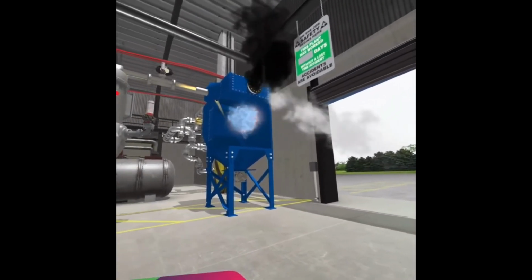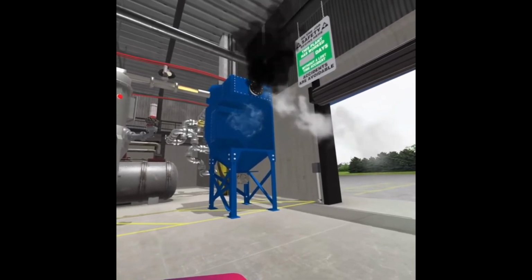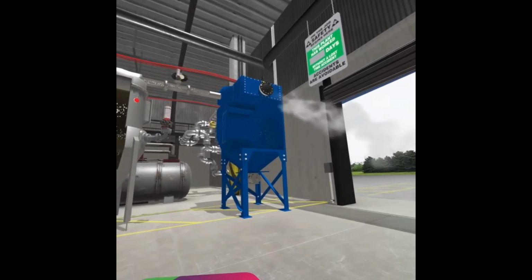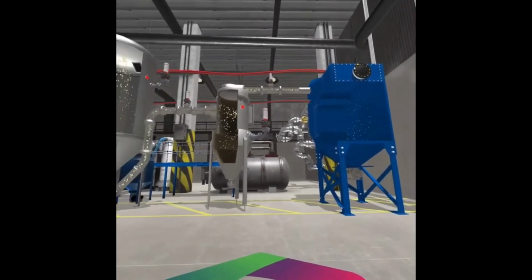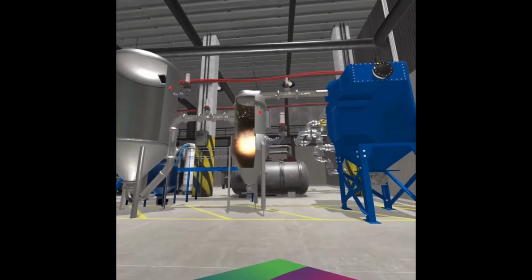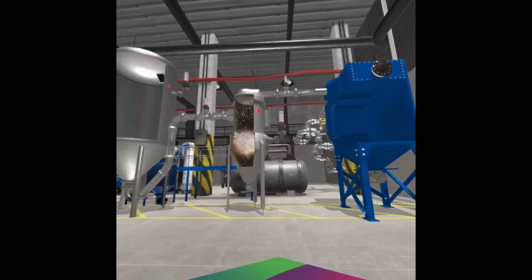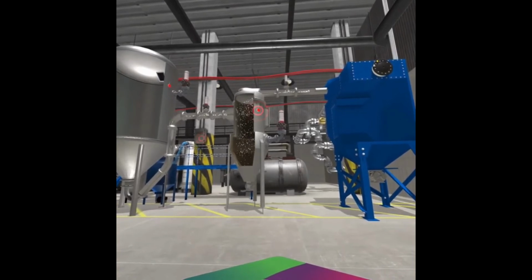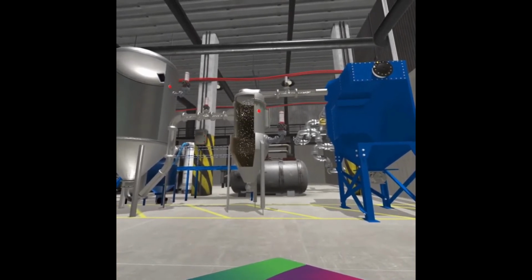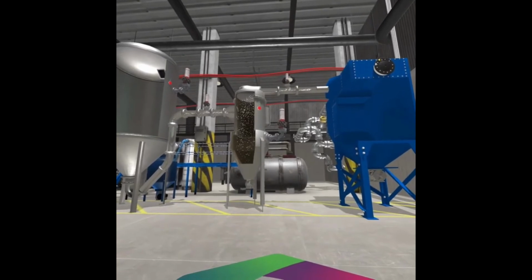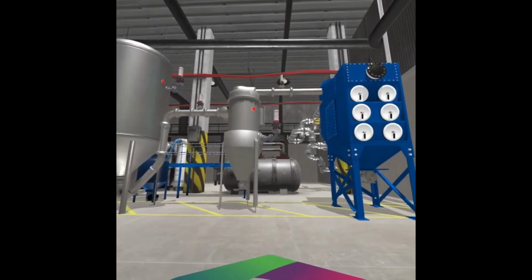But what if the ignition source finds the perfect conditions for an explosion in a different vessel? Let's take a look at an explosion which occurs in the cyclone. The smart DS intelligent pressure sensor detects the pressure wave at the earliest stage and then communicates this to our control panel. Within milliseconds, the controller actuates the high-speed suppressors. They deliver a suppressant which stops the combustion process before critical pressure levels are reached.